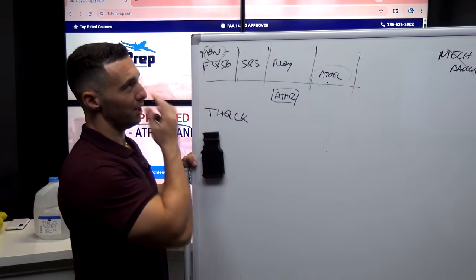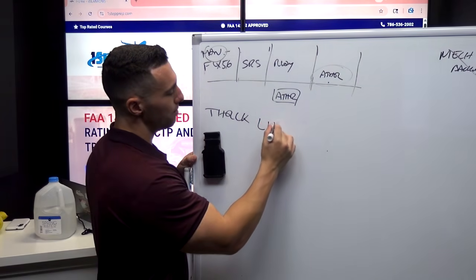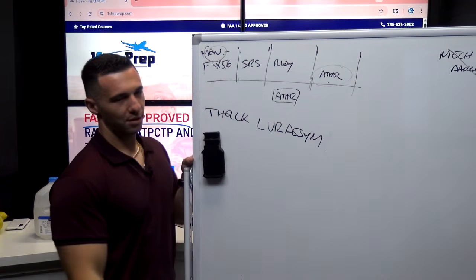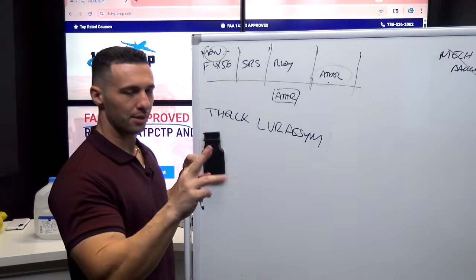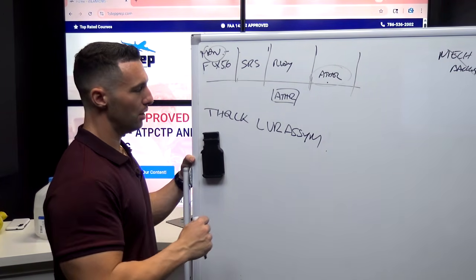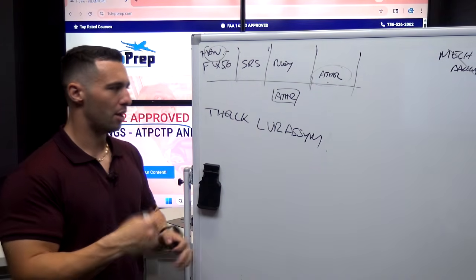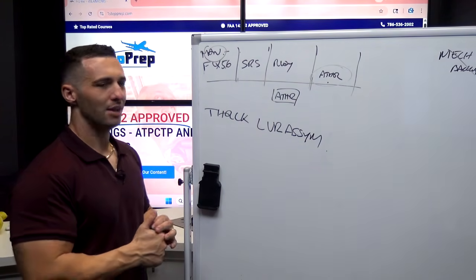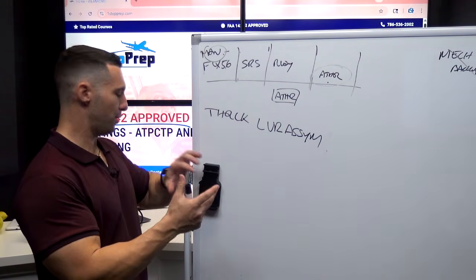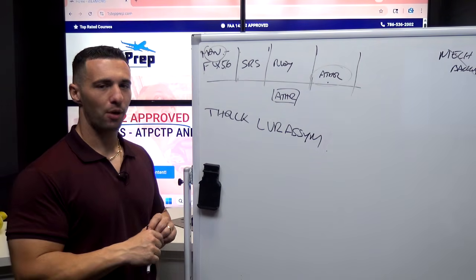What else did I not cover with the auto thrust? I guess another indication you could have is lever asym. That obviously tells me that the thrust levers are asymmetrical. They're not married up together. So the auto thrust is full of different things in terms of alpha floor, alpha lock, TOGA lock, the protection, thrust lock, a great many things that from an oral perspective you can extract quite a few questions out of just this auto thrust system.